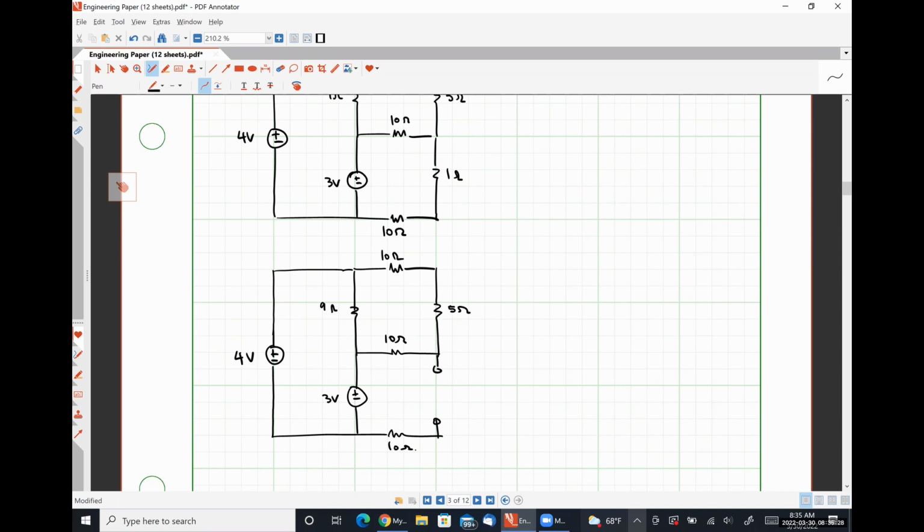All right, so the Norton equivalent current is the short circuit current, which means we simply short out our terminals and then measure the current flowing through that short circuit. So what analysis method would you guys like to use to determine this current? Mesh, okay.